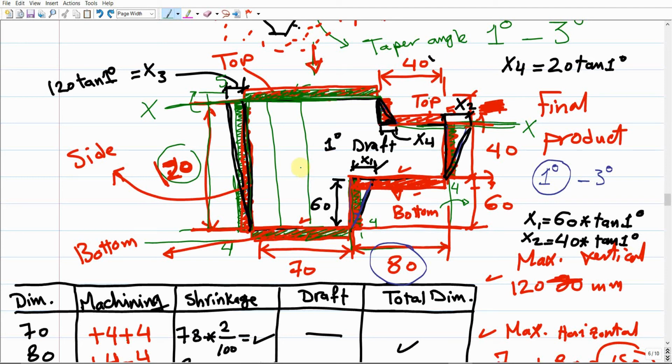But forget about the details of the core sand for now, and just focus on the fact that we may have a core, and this core would be located either vertically or horizontally in the sand mold during the casting process. Generally the core can be any shape, any internal opening, but the key idea is that it should be internal.